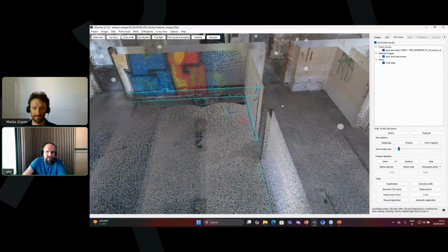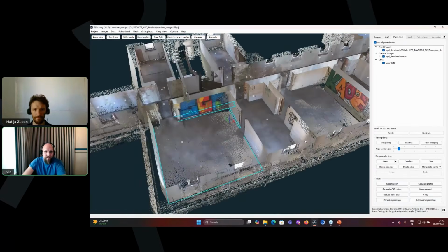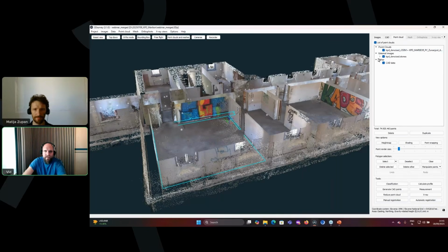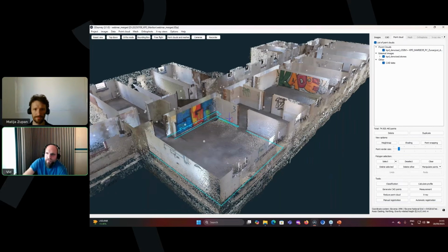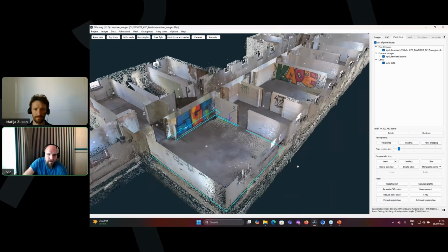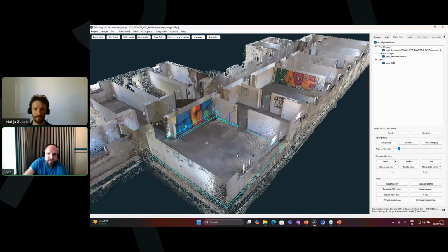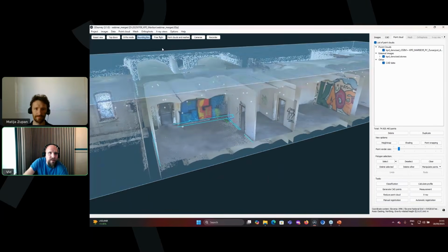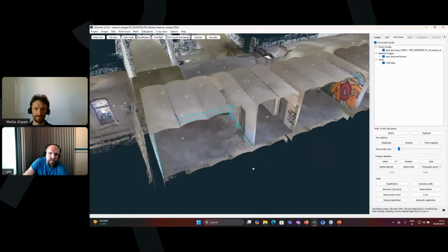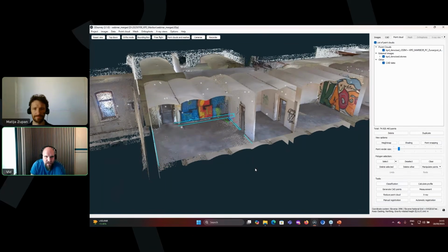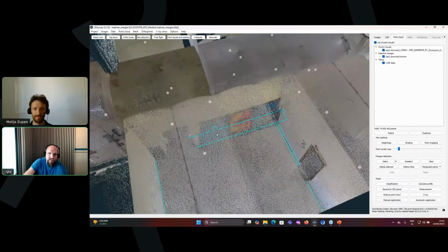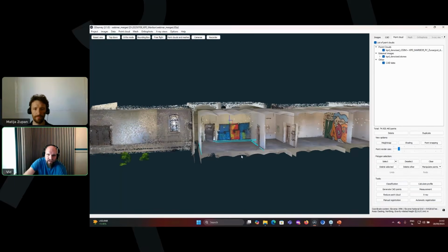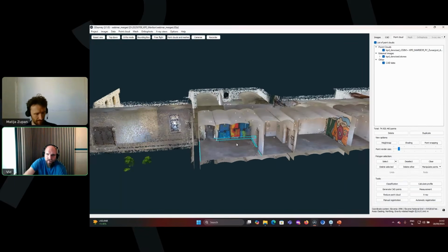Right, so here they did this like that. They also took out from the model the heights of the rooms. In this case, I think the workflow they used was to do the height model. They just used a bounding box. We'll now take this one in like that, move this one to the top. So the BIM model that they are creating does not allow creation of arcs like that. So the trick they used in their software was to calculate the average height of the roof section.